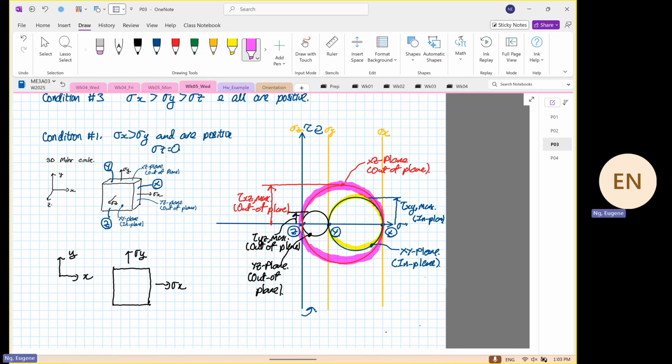When you sketch this out, you realize that even with stress Z equal to 0, your shear stress is higher. So now the maximum shear stress occurs where? Not in plane. Now your maximum shear stress occurs out of plane. Okay, so that is the reason why we're doing the real stuff, not the Mickey Mouse crap that's going around.